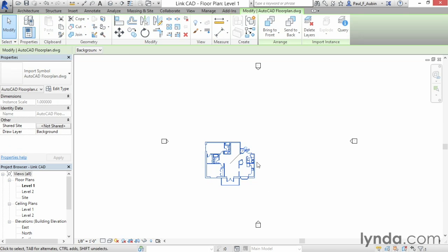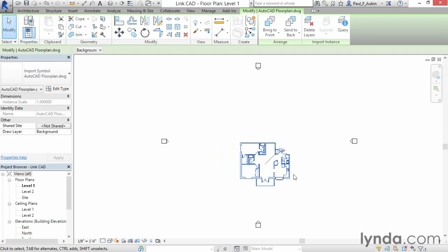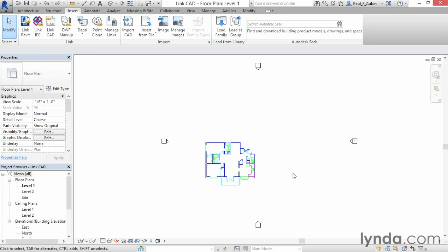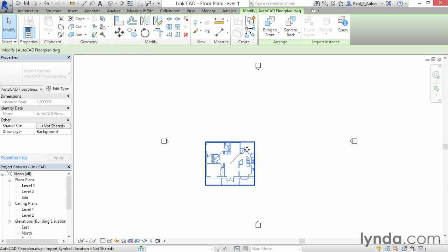the Revit project. And there's this little pushpin icon that appears right here that's designed to prevent you from accidentally moving this. So notice that if I tried to drag and move this file, I can't actually do that as long as it's pinned. Now, if for some reason you decided you did need to move it, you can simply unpin it, and then you're free to move it. But I'm going to do Control-Z and undo that, select it again, and repin it.